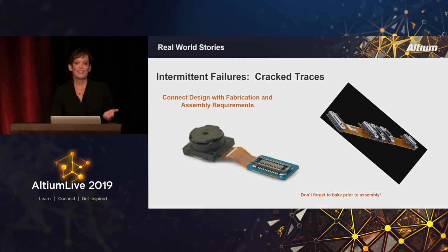So this case had a flex with a very heavy circular connector right in the middle. So the designer added the FR4, as we would all recommend to give stability to that, fabricated the circuit, it went to assembly, and the guy doing assembly is realizing that the FR4 is great, but it's still kind of wobbling enough that they're getting cracked traces. So he came up with what I think was a pretty creative solution to that, and added a piece of FR4 to the top side of the circuit. So now you got FR4 sandwiched on both sides of that polyimide, and then applying that heavy circular connector.